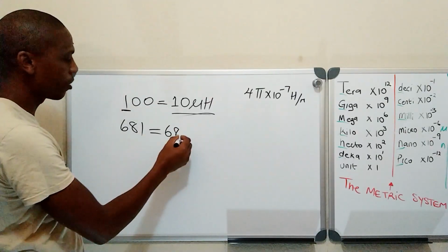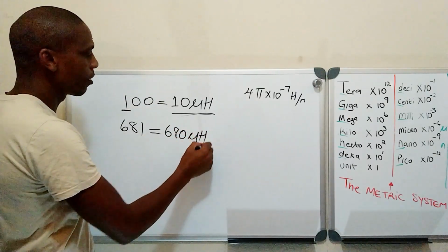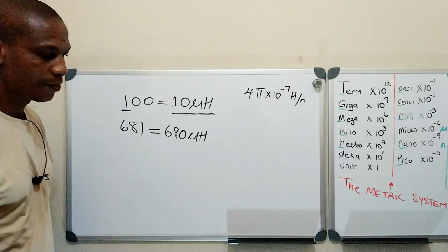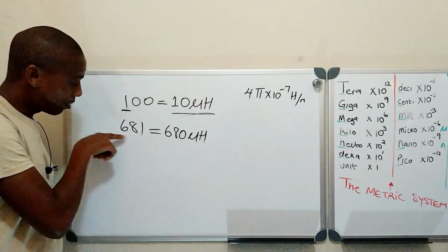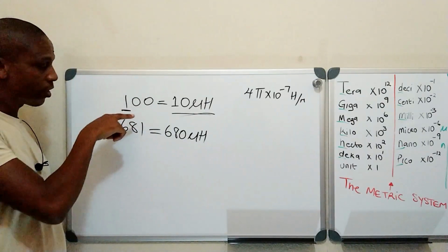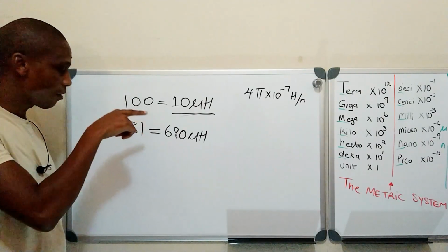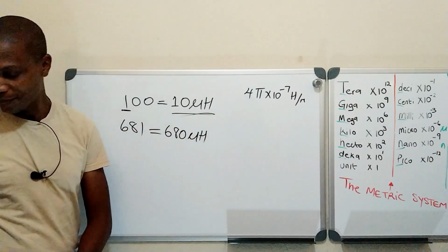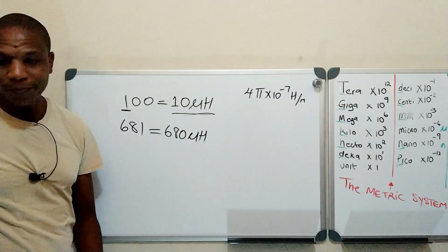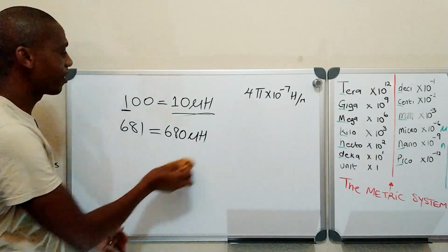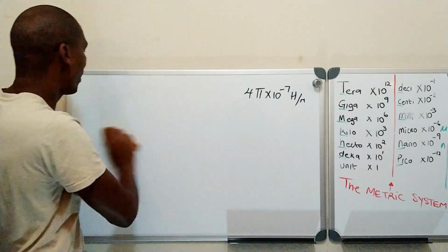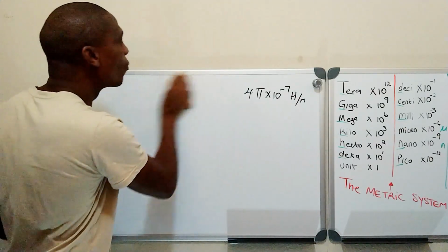Since there's a 1, that means there's a 10 microhenry. You must practice, ne? It is the same. You read the numbers the same way for surface mount, resistor, surface mount, capacitor, surface mount, inductor. The calculation is the same. Ne? You must just practice, ne? Practice, practice, practice. Now we're going to make our own inductor.